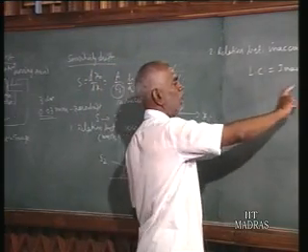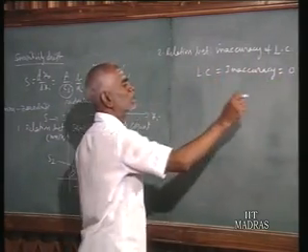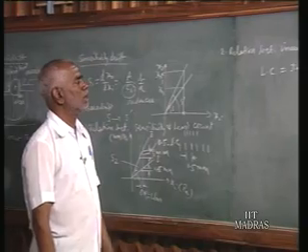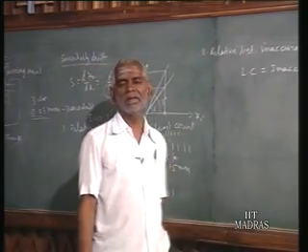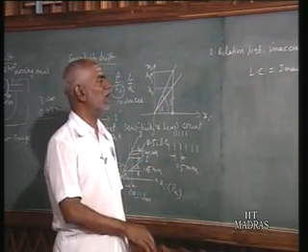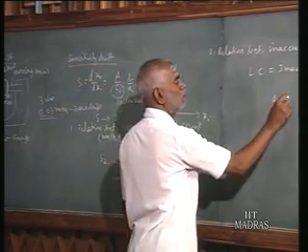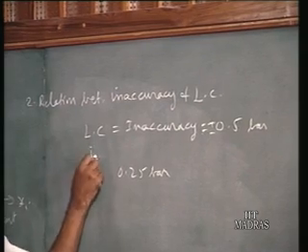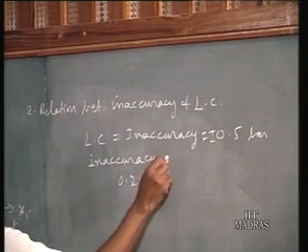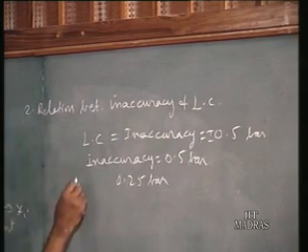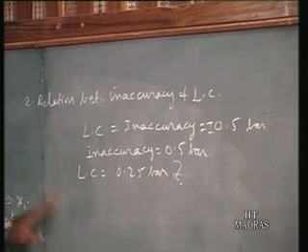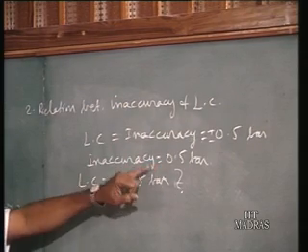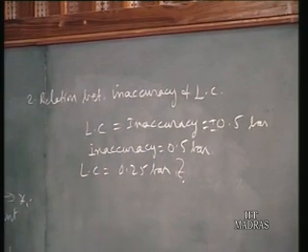So, for this instrument with a least count of 0.5 bar, the inaccuracy is also plus or minus 0.5 bar. This is the norm which we have to adopt in the design of instruments. Suppose the inaccuracy is 0.5 bar, which the designer has found out. Can he have a smaller least count, say 0.25 bar? Is it permitted? It's not permitted, because when the error is 0.5 bar, dividing the error, reading within the error, is not permitted. There is no sense in reading below the inaccuracy.